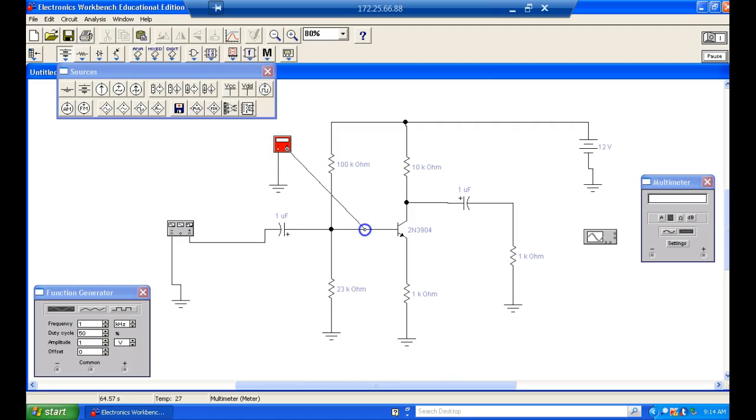So I'm seeing that wrong, guys. Thank you. So we got about 1.2 volts right there. We'll see what we got. And let's go over here on the collector and see what we have on the collector. Oh, wait a second. Let me get rid of this. No, we need 0.7 of a volt more positive over here.